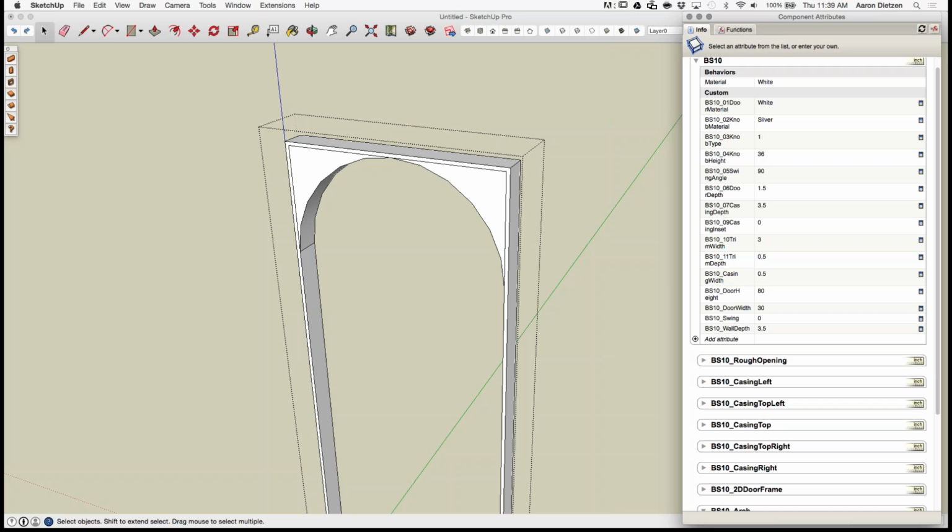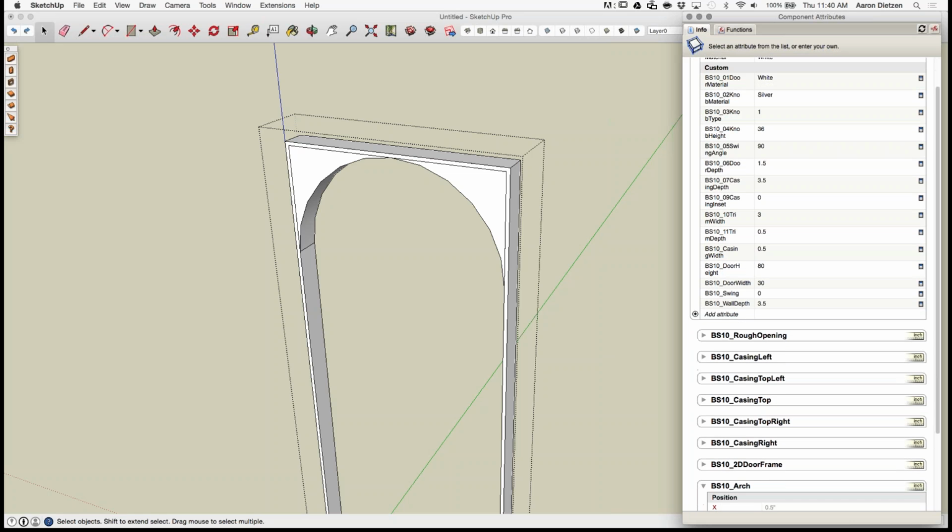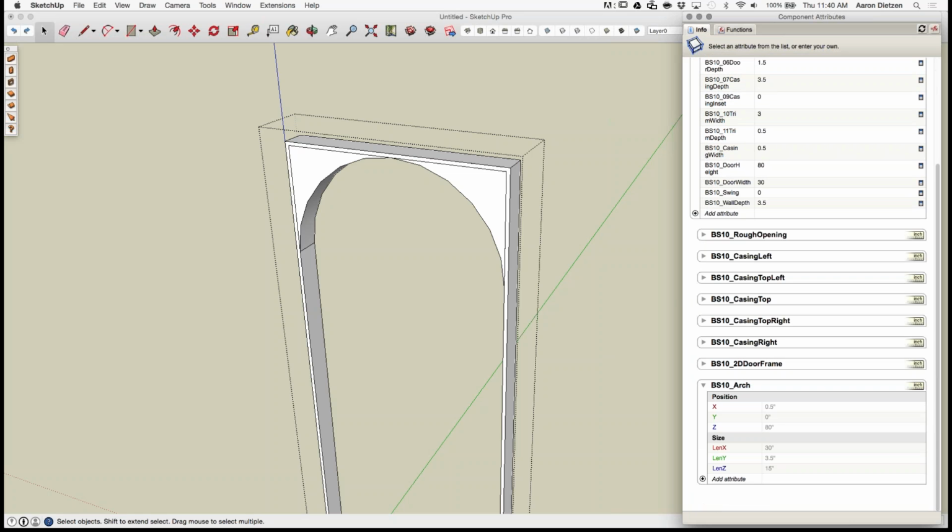So it's real important that I can use these values, but I don't ever want to go in and change how these attributes are named or formatted or anything else. And again, all this stuff is in that document that is up on the website. In fact, it's probably overly cautioned. I think four or five times it goes through and warns you about making changes if you don't know what you're doing. But that's just because if you do end up making a change to a dynamic component that Build Edge doesn't know about, it can stop it from working, which is not good.